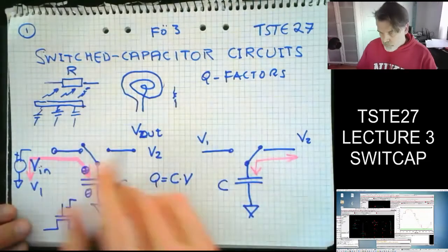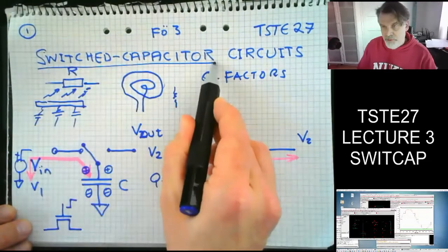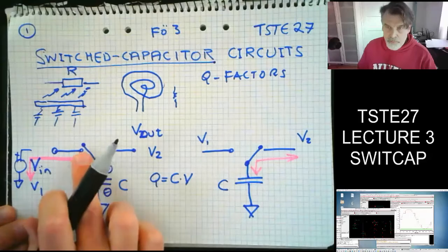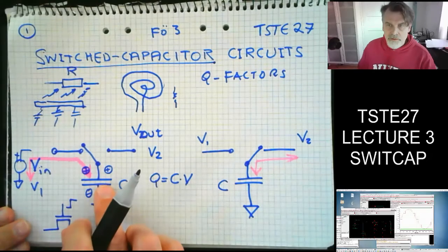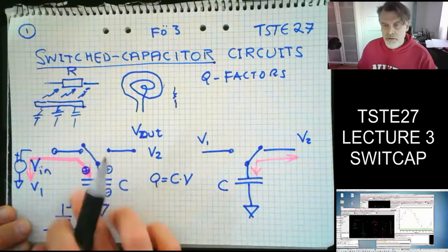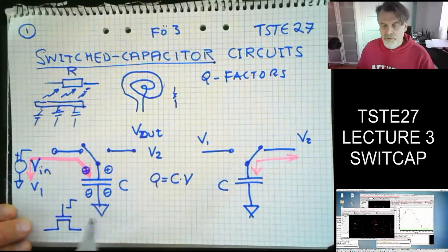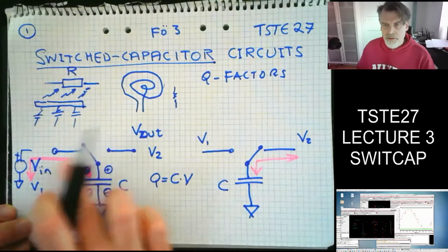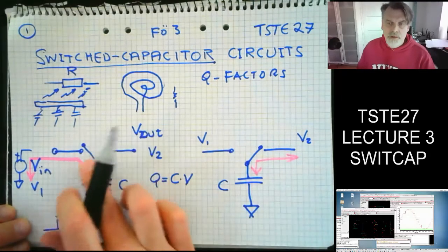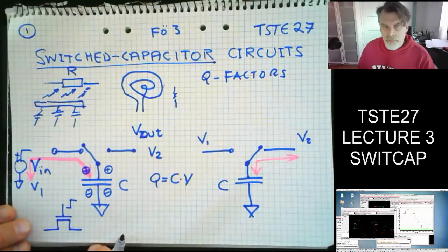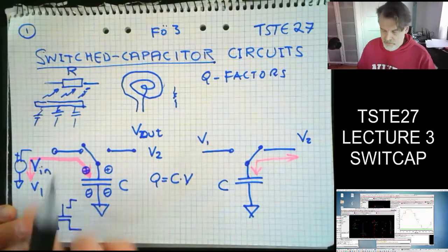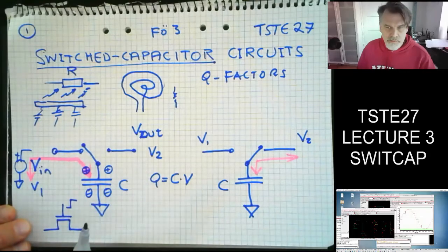So conceptually, with switch capacitors, I do have simple ways of implementing the switch with a MOS transistor. I can take some metal plates, put them close to each other, and then I have a capacitor. And then I'm able to switch back and forth in order to move charge up and remove charge. And if you think about this, this is actually acting like a resistor.